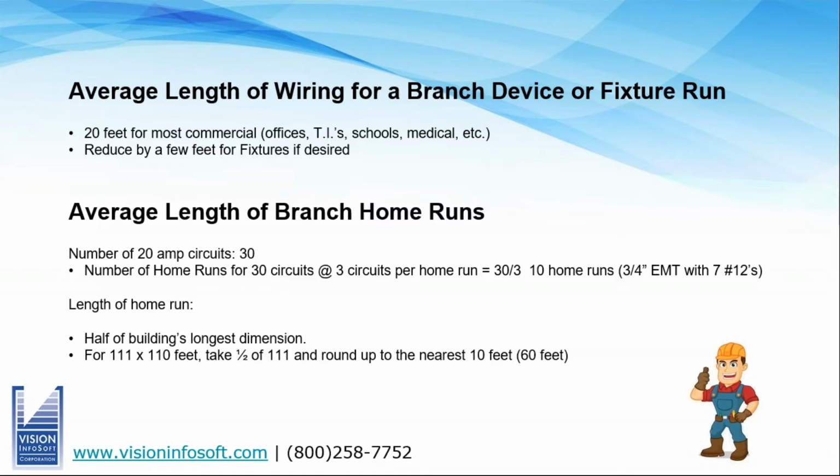And I would say, if anything, you can go a little bit lower on fixtures, because typically fixtures are staying at the same elevation on the drawings, if you will. Every receptacle and switch you have to drop down to or come back up to the ceiling from. So typically receptacles and switches have a little bit longer length. But if you use a 20-foot average, again, in a typical situation, you're going to be fine. And here's what I mean by a typical situation.